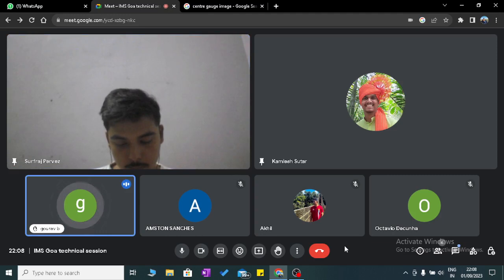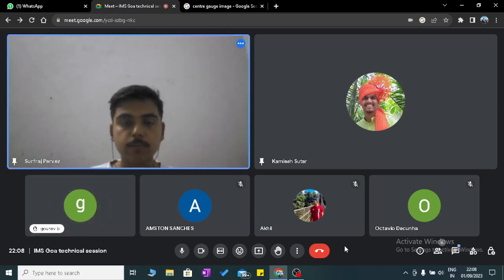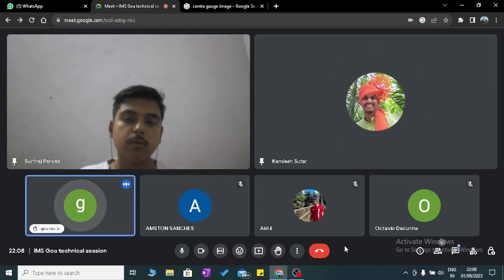Yes, please. I will give some questions, like how you make the single point cutting tool. It can be asked, because when you do thread cutting, the required angle will be needed between the threads. We grind it first as a single point cutting tool, and we measure that with an angle gauge, which is the thread angle gauge. Yes, this type of question can be asked as a cross question.